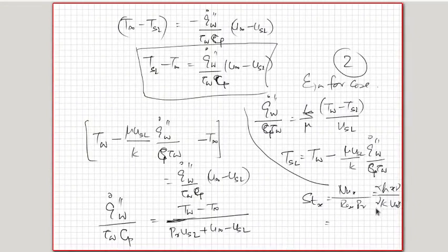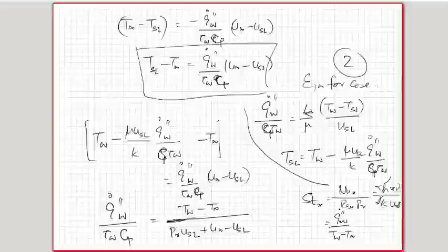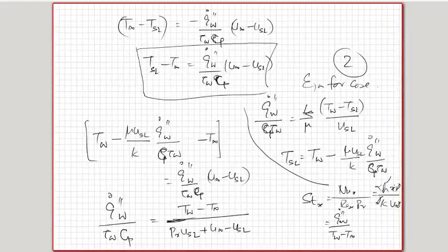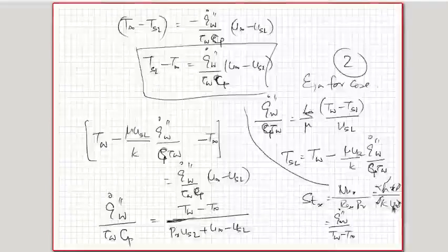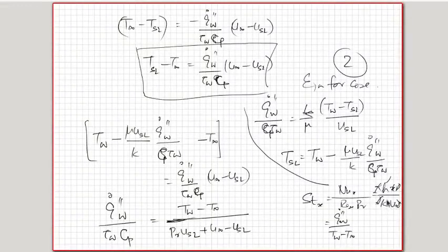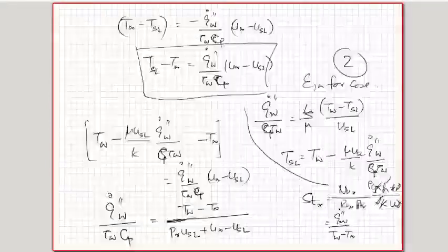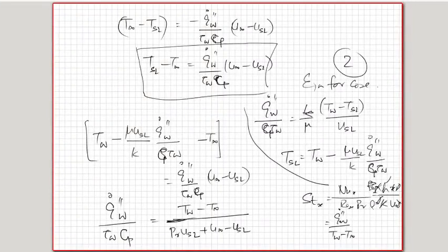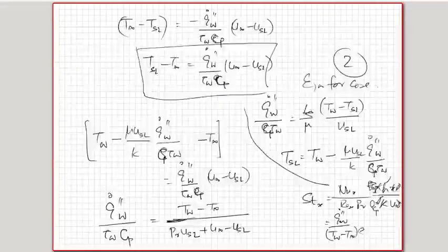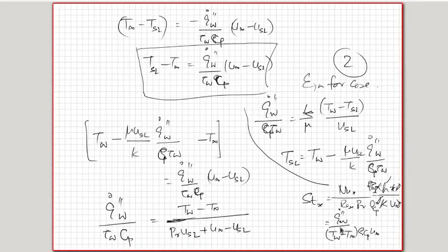So if I substitute this, this H is Q wall divided by T wall minus T infinity. Okay, this nu gets cancelled here, this X gets cancelled here, so you have a K and U infinity and alpha. So this alpha, if I cancel, then this gives a rho CP below. So you actually get this multiplied by rho CP U infinity.